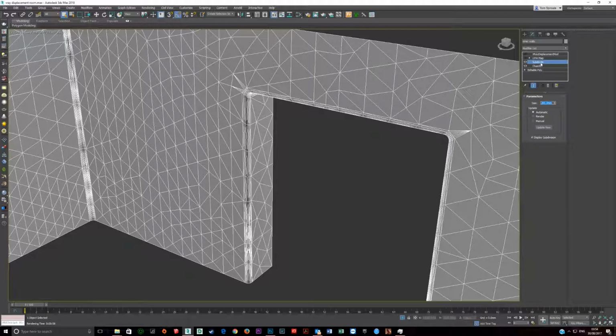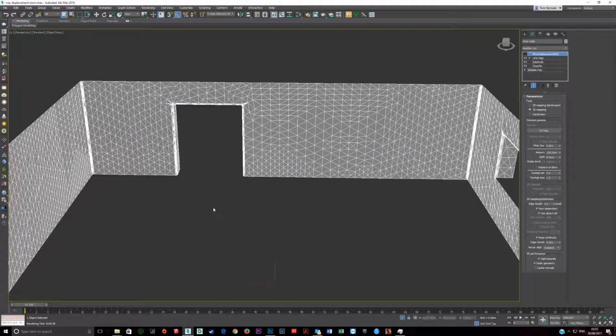If you don't have subdivide, or you don't have a mesh which is already subdivided, let's take a pillow for example. A pillow normally has lots of boxes. That's fine. That's going to work with displacement. If you don't have something which is already in small sections, you need to subdivide it, or your memory use is just going to go out the roof. I've got a UV map on here and I've got a V-Ray displacement mod.